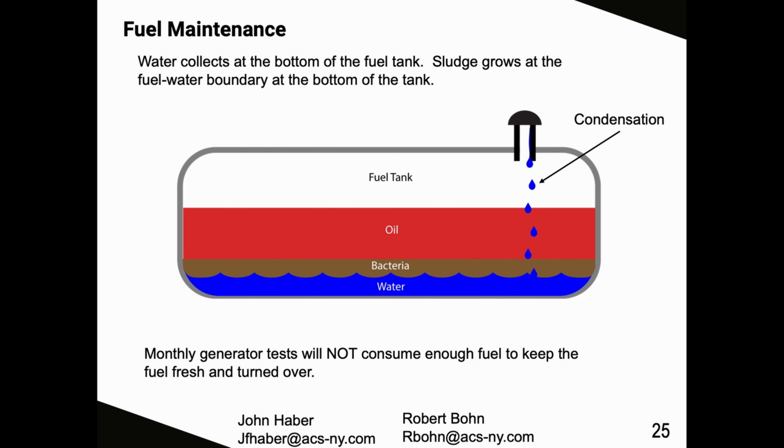Another thing to note about the water in the bottom of the tank, if that is allowed to sit for a long period of time, does not bode well for these steel tanks that are put in everywhere. Another thing to mention is that the ULSD, ultra low sulfur diesel, are even worse for steel tanks. So if you let that water sit at the bottom of your tank for a long period of time, it's going to erode the tank and allow for premature failure.